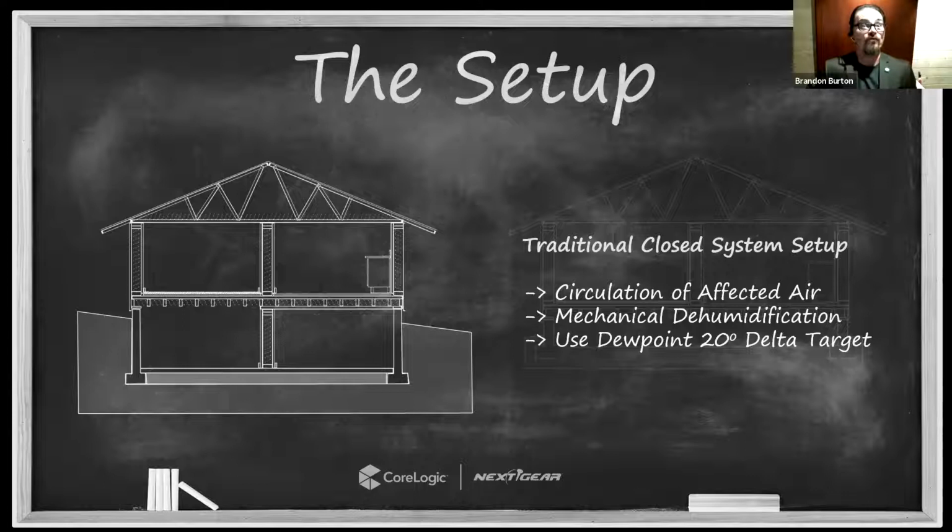I like warm air for supporting evaporation, but it does the opposite thing to my dehumidifiers. The warmer that air is, the more difficult it is for them to create low humidity. And in an above ground space where my temperatures are more evenly affecting the environment, that's not as significant a limiter as it is where I'm dealing with a lot of heat sinks with materials that are very difficult to warm up, right?